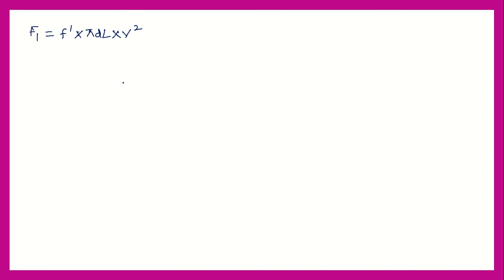So when there is friction, we expect a turbulent flow, and according to Reynolds' experiment, the friction is directly proportional to v square. That's what we are writing here. So finally I write this equation as F dash into P into L into v square. I wrote pi d as P, because we know that perimeter is pi into d. Let this be our equation number 2.